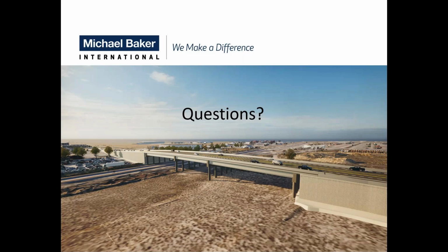Okay, and then the next one states there is a gap between the abutment columns and embankment behind. Was it bridging this gap? The approach slab is bridging that gap, and the gap was there to allow for that seismic movement, and also to be able to work behind that. But basically for that seismic movement, there's that gap behind the back of the abutment cap and the wall.